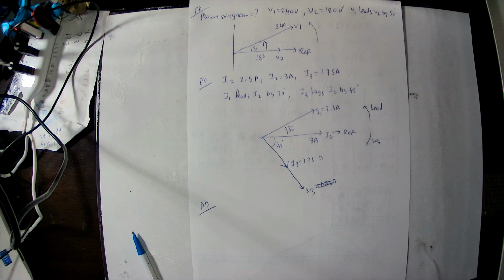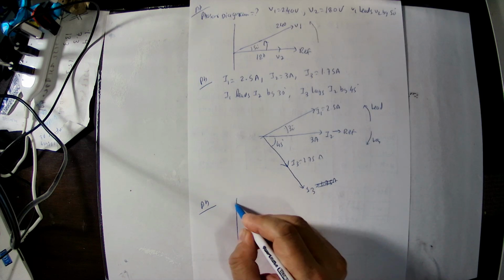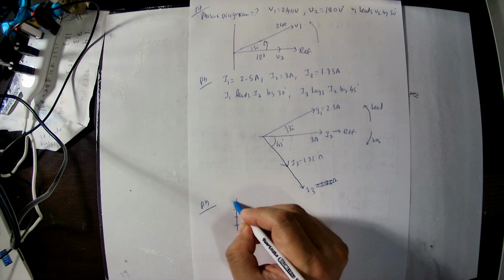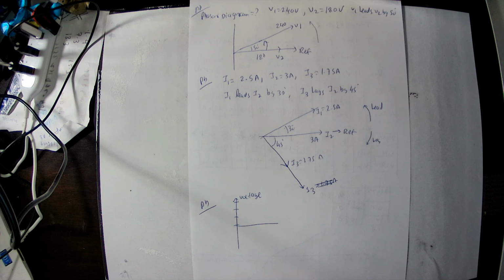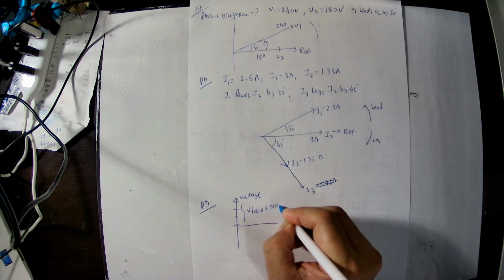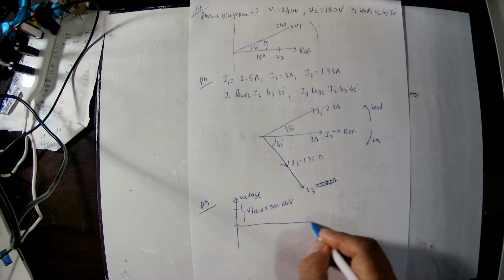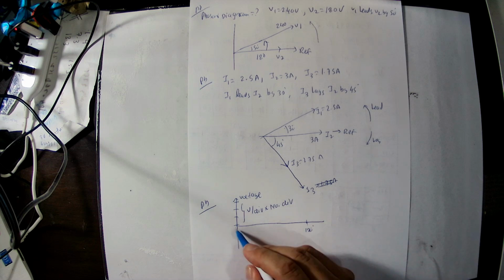In this case, the vertical represents the voltage. So we multiply the voltage value, volt per division, by the number of divisions. Horizontal, here is 180 degree. One wave is going 180 degrees. So you can calculate the time per division.